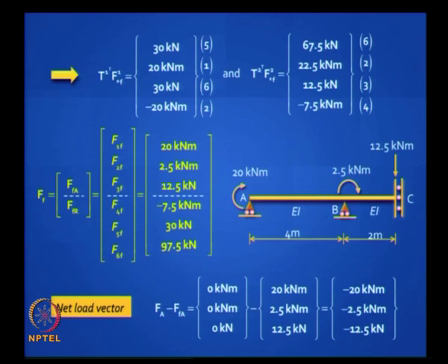It is very effectively done, because you can do matrix analysis only if you are dealing with nodal loads, because the matrix has only vectors which have discrete entities, so your coordinates are limited. Next you generate the element and structure stiffness matrices.